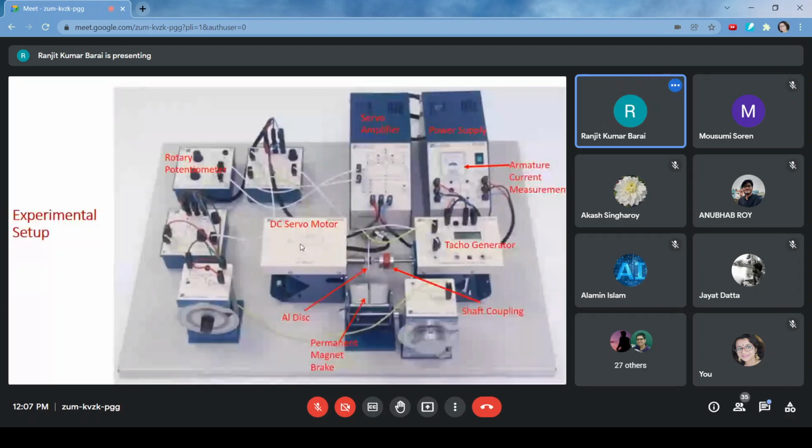You can find many audio amplifiers of very high power rating. If you get a substantial power out of an audio amplifier, that can also be used as a servo amplifier, because audio amplifiers are very linear, very precise amplifiers. The servo amplifier is also a very precise linear amplifier with audio frequency bandwidth, because the frequencies of interest in a control system lie within the audio frequency range, almost always, from 0 to some 20 kilohertz or so.